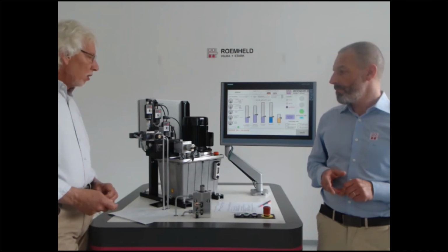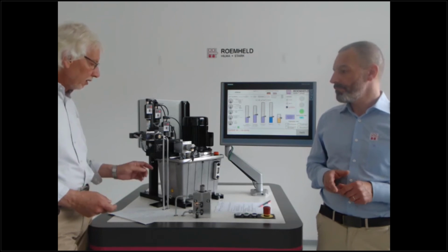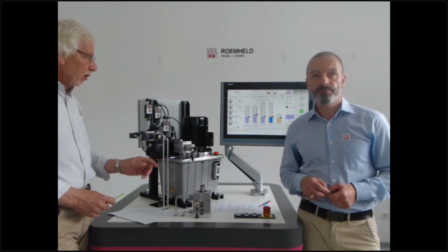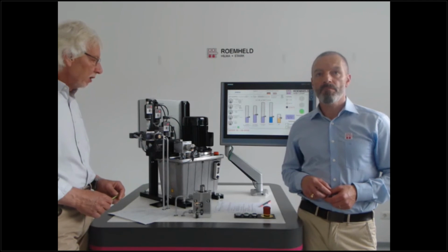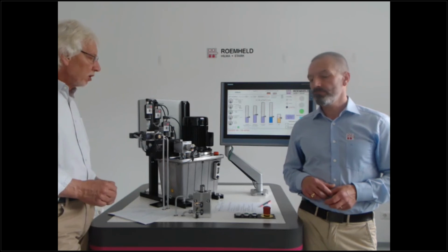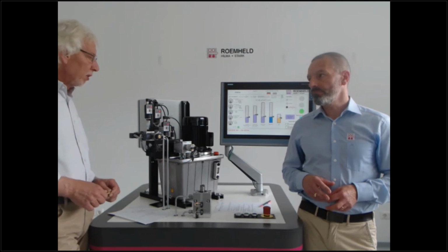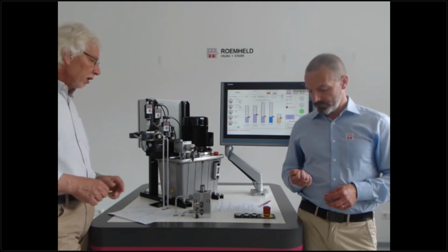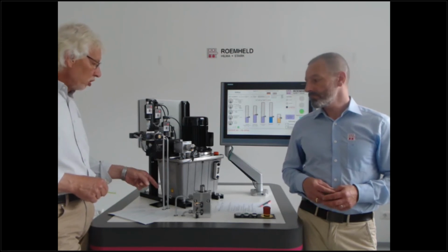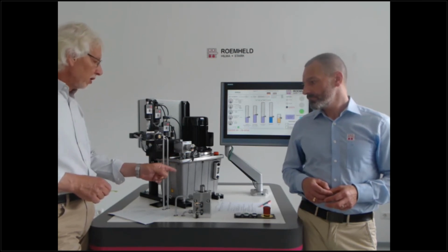In nearly every power unit, normally we have to change the inside piping of the power unit, because the measurement sensor must be flown through by the oil, and therefore it is possible to make our own circle for the measurement equipment. Normally we have to change the pipe inside the oil tank so that the oil flows through the sensor and back into the tank.